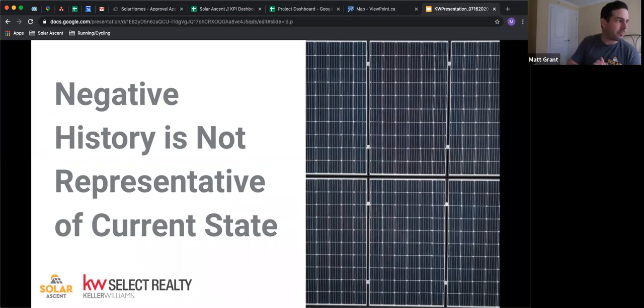On the metal roof, instead of tar, we will use clear flex on the back of the plates, and they also come with blue skin on the back, so any penetration is locked in pretty tight. We like to be really, really sure. But in terms of leaks, it's pretty solid stuff, the way the installations are mounted.